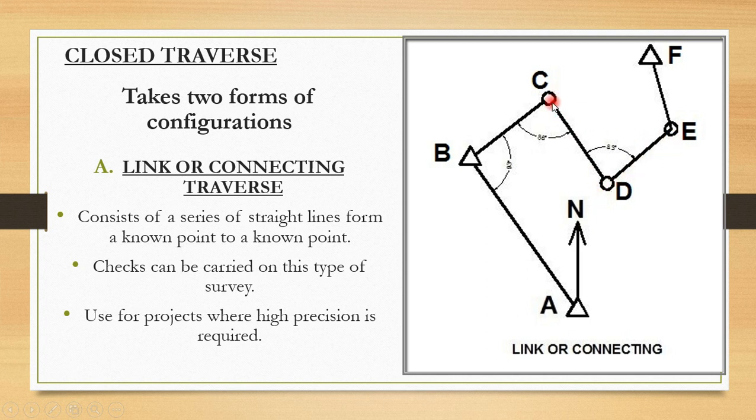The accuracy of the points that have been established will depend on the closing on the known points. That is, if we are starting from A up to F, if our surveying closes perfectly at point F, then we will know that points C and D have been surveyed correctly. Otherwise, you may need to do the retraversing, or conduct the exercise once again.